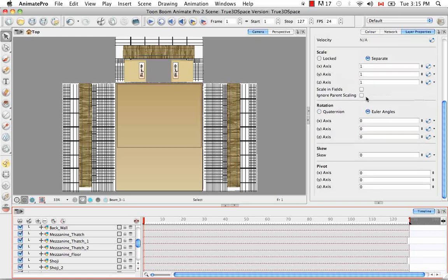Euler, on the other hand, is good for when you're piecing together objects to create your scene. You're able to rotate them individually. Like I said, if you add a keyframe to any of these 3 axes, it will remain only on that axis. These 3 axes act individually, and they have their own velocity as well. So in terms of making movements using the Euler angles, it can be a bit choppy, so you do have to look out for that.